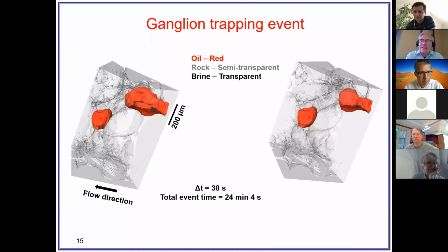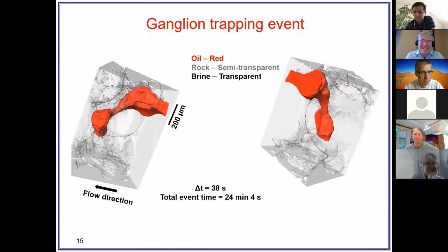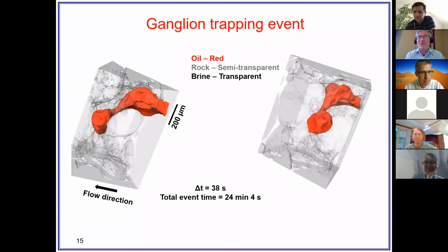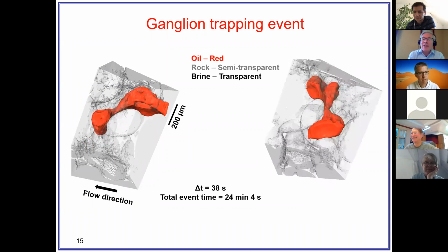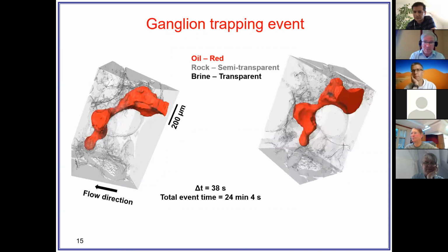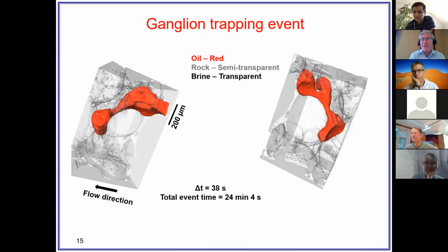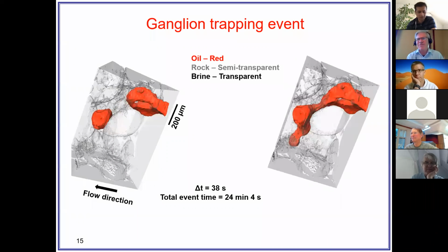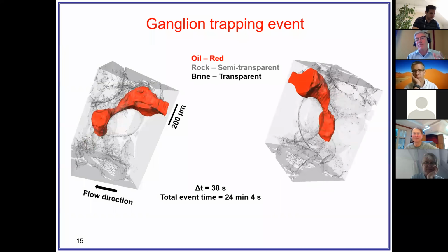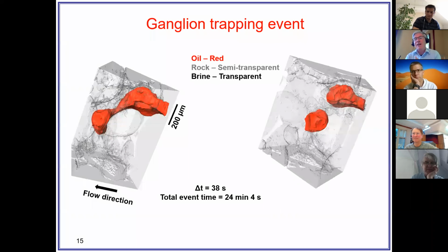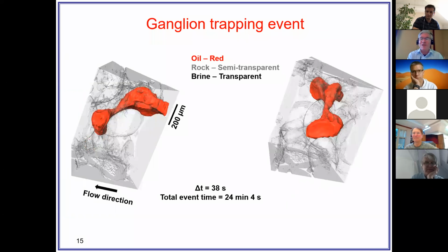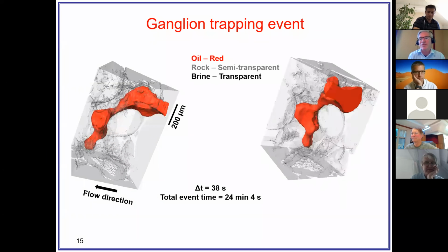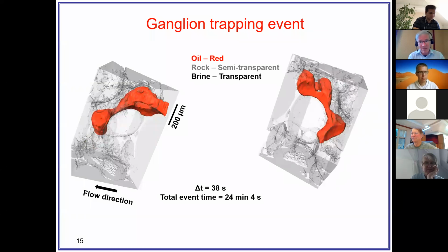Yeah, this is again a recurring question. People say, well, you understand a lot about the small scale, but our reservoirs are kilometers across. I think it is important because it's understanding local displacement efficiency, right? And hitherto, people have just assumed that that was something measured and changed in a history match, and focused on larger scale heterogeneity. Larger scale heterogeneity is clearly important, but now we have a much better understanding of one of the other things, which is what's happening at the small scale. So I think that they're complementary.